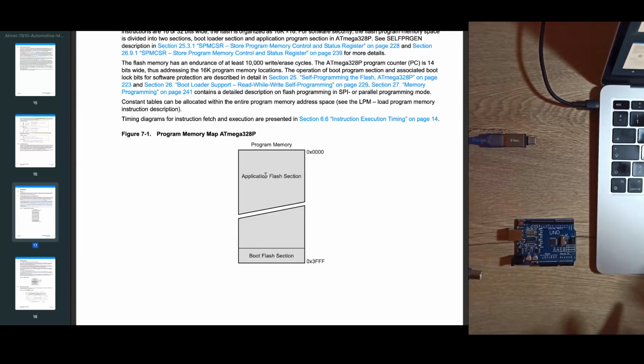All right, so we're going to see how I structured my bootloader program. It uses the same protocol as the OptiBoot bootloader program that is usually shipped with the Uno board, but it's a little bit smaller and a little bit different.